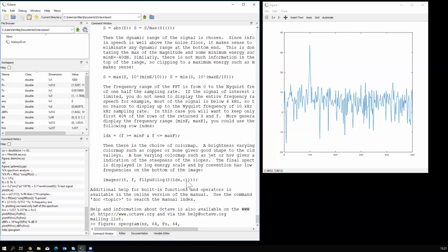We can artificially add zeros here to get more spectral resolution, since this mapping is always done linearly over however many points the whole range was divided into. So you just divide the sampling rate by the number of points in the window, and that defines the frequency resolution of this picture.